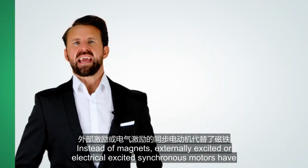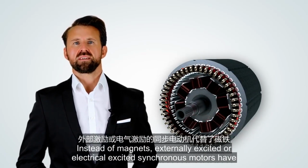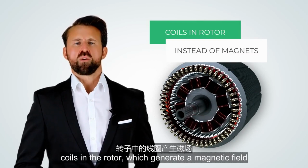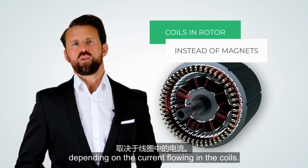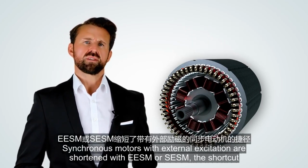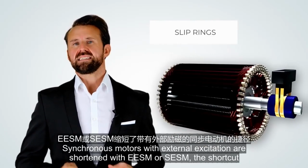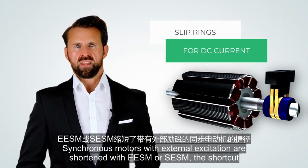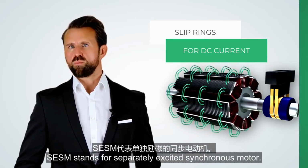Instead of magnets, externally excited or electrically excited synchronous motors have coils in the rotor, which generate a magnetic field depending on the current flowing in the coils. Synchronous motors with external excitation are shortened with EESM or SESM. The shortcut SESM stands for separately excited synchronous motor.